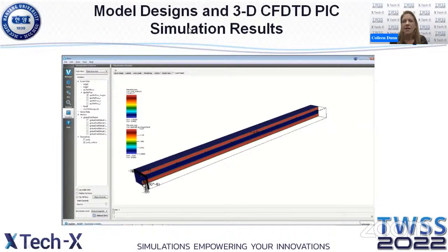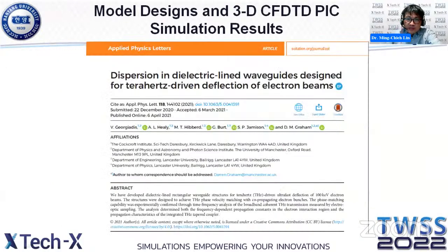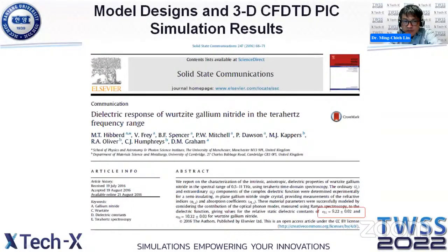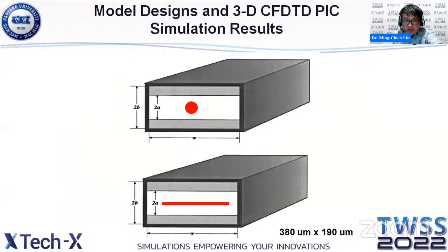Thank you. We have a kind of clarifying question. If A equals B, doesn't that mean that the waveguide is built? A equal B. Okay, I see. You mean it's totally filled, or I think my parameters are defined... Let me make sure. I think A and B correspond to width and height, and we use D to... Oh, okay. Here I use A and B. Sorry. Then you are right. If A is equal to B, then it's totally vacuum. Or if A is 0, then you have a totally filled waveguide. Then yes, you can recover TE and TM modes. I'm sorry, I misunderstood the question. Oh, that's okay. It's always a challenge here.